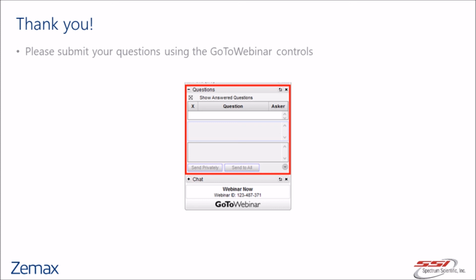So you might put mechanical marks for use with, say, an alignment telescope, something like scribes on the part in specific locations. Or outside the clear aperture, put some fiducial marks or flats on it. If it's a round part, you might put a flat somewhere on it to reference the back. And these might be polished flats that a distance measuring interferometer could use, for example. Yeah, they could be polished.